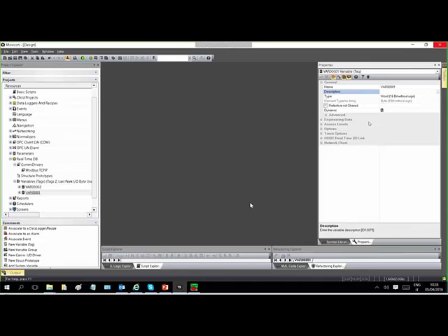You can add a description, could be important. Variable type: bit, byte, with sign or without sign, word, double, floating, string, array. In case of array, you should define here the address, so the length of the array, with which you can add the member of the array between brackets in this point.